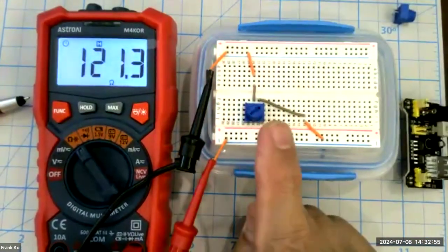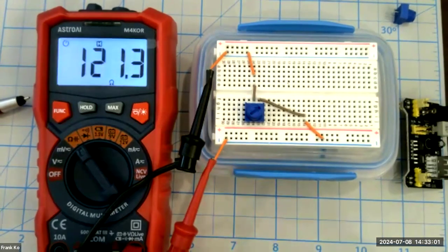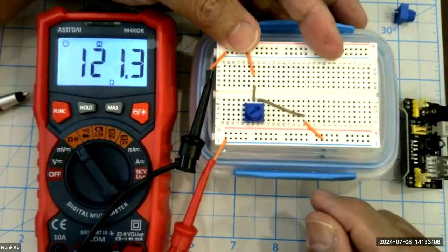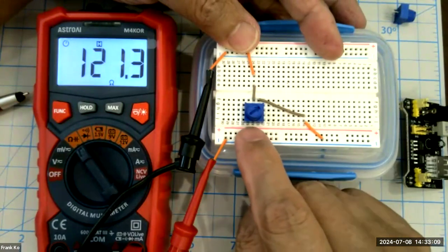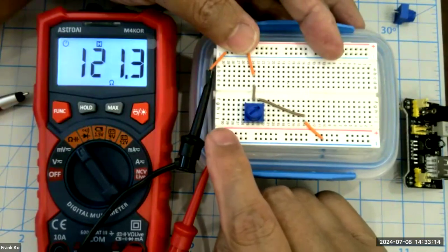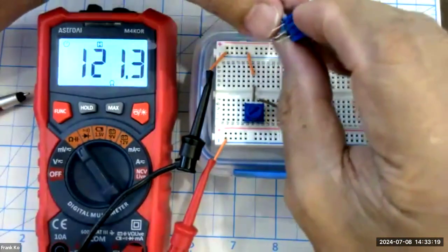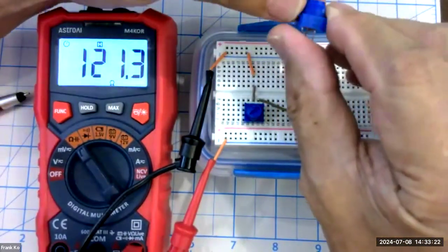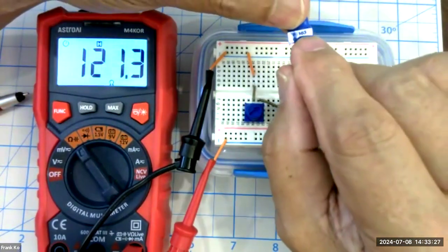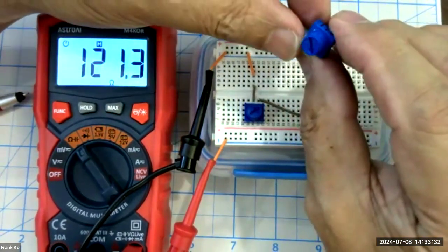So I've dialed this in right now to 121 ohms. We really need 166.6 ohms. And with this particular style of potentiometer, it's a little tricky, and I'll explain why in a moment. Some of these are what we call linear pots, meaning it gives me a very consistent change from one end to the other end of the potentiometer range. And let's see, these guys are rated at, let's see, what's it say here? It looks like it's a 1 k ohm pot. 103 is the code for 10 k ohm. Excuse me, a 10 k ohm pot.